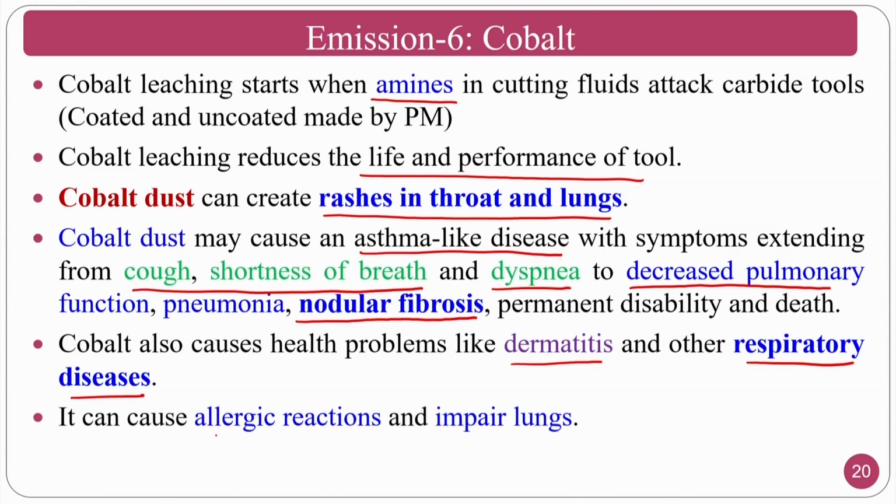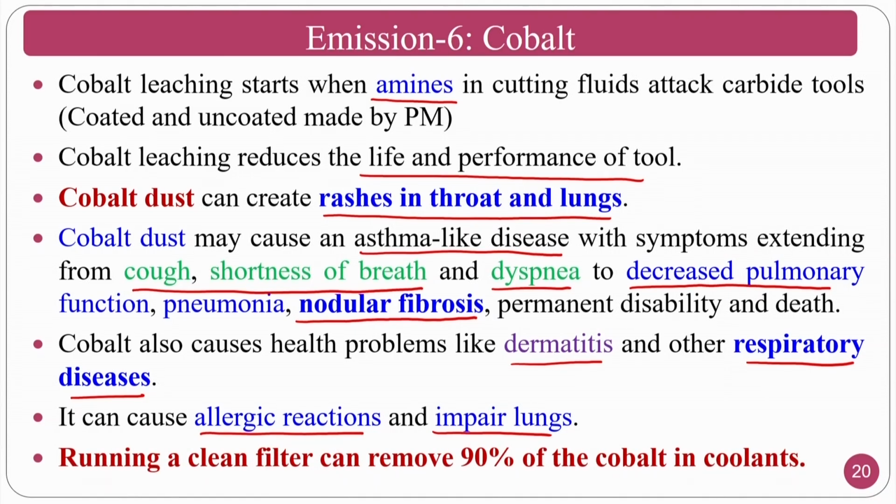It can cause allergic reactions and impair lungs. Because of the respiratory problems, you may get a lot of problems. Running the clean filter can avoid 90% of cobalt contaminants. You have to run the filter so that these micron-size particles will be filtered out, so that they won't come in the next go of the cutting fluid action.